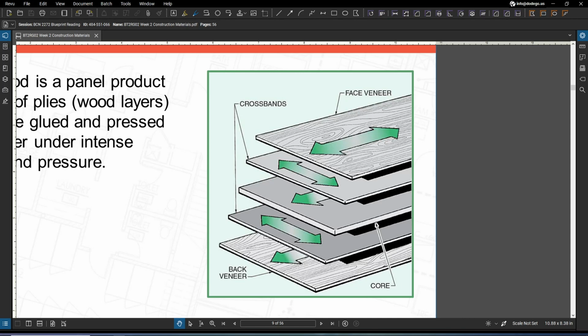And various veneer grades, which include N, A, B, C, C plugged, and D, are going to be utilized for different applications. Now, the highest veneer grade, which is N, is either 100% heartwood or 100% sapwood, and that's going to be intended for your more natural finishes. Now, the lowest veneer grade, D, contains large knots and knot holes and is intended for your rough applications.